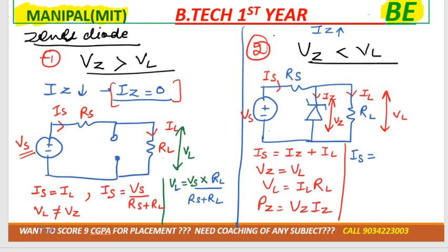Like V by R, right? So if we want to calculate IS, then resistance would be RS. Yes or no? Voltage would be VS minus VL, because total voltage, suppose you have given 100 volt and from that 20 volt is consumed by the Zener. So how much is the left voltage for the RS? 80 volt now. So that's why we are using this formula. IS would be equal to VS minus VL by RS.